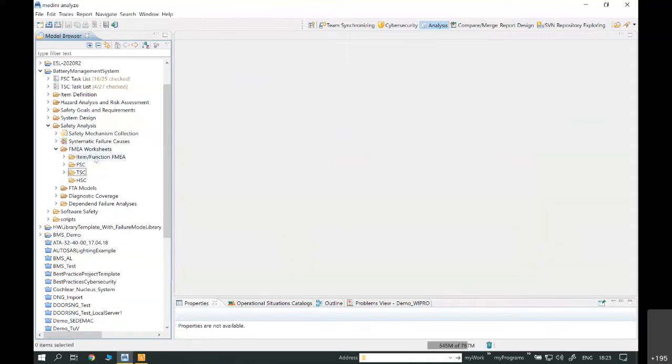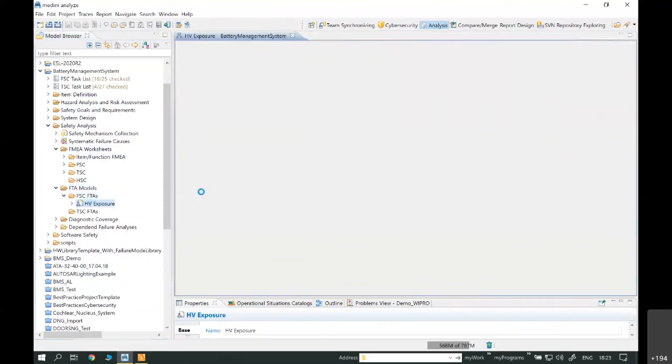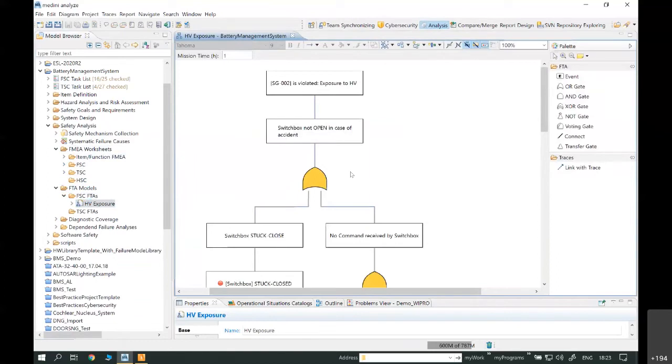Okay, so that's primarily looking into FMEA, and we can also quickly look into the FTA analysis. The fault tree analysis is very important, and it complements the FMEA analysis. As we all know, FMEA starts from the basic leaf level events, adds up their failure modes and shows the results at the top level, whereas fault tree analysis looks at the top level undesired events and then finds the root causes that could contribute to that top level effect.